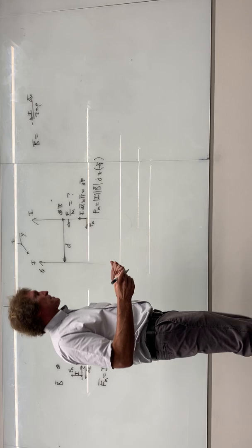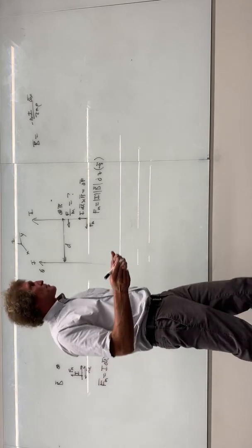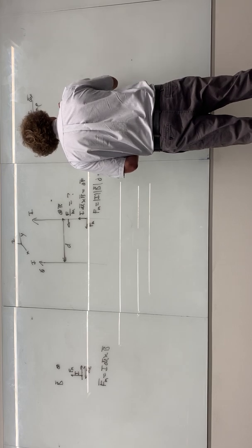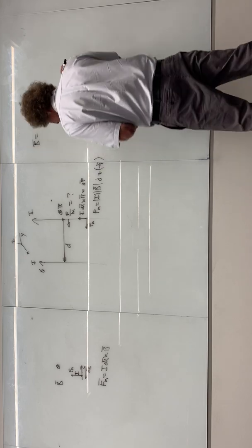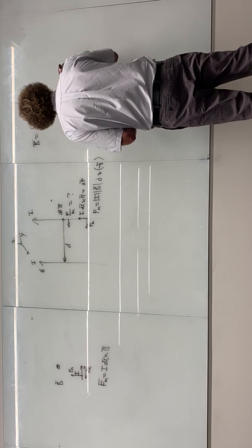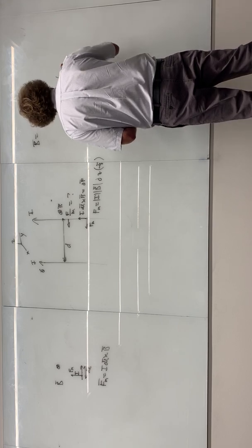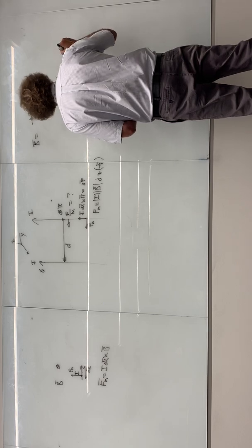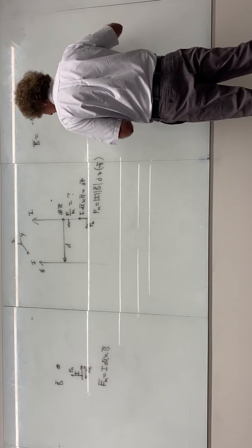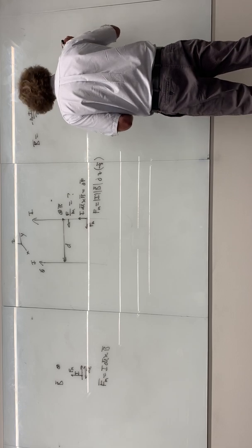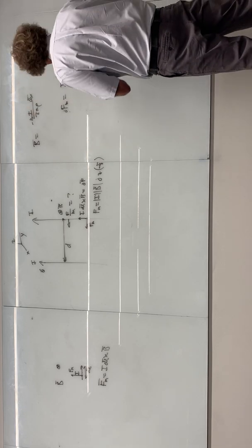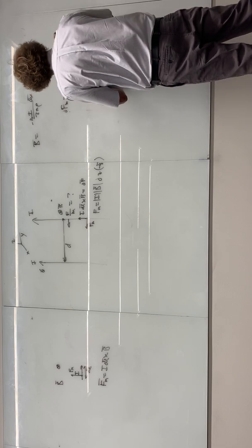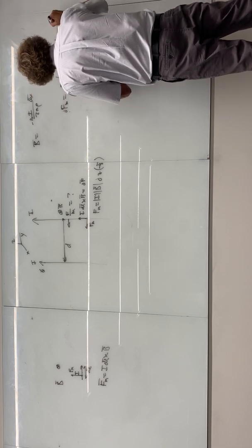Do y'all follow me on that? So if I go ahead and put in the equation, I could say the magnetic force on that wire per meter would be equal to I times B. Well, B is equal to mu 0 I over 2 pi rho, where the distance in this case is just d. When I do the cross product, I'm going to have dz here, and then I'm going to have minus ay direction.